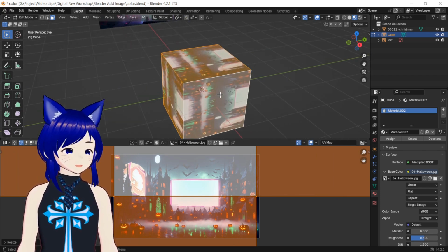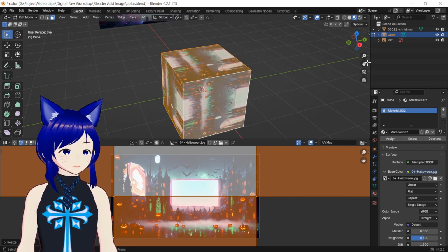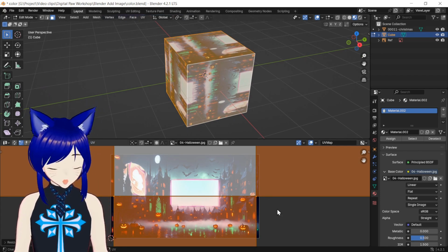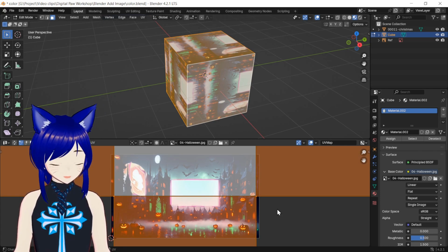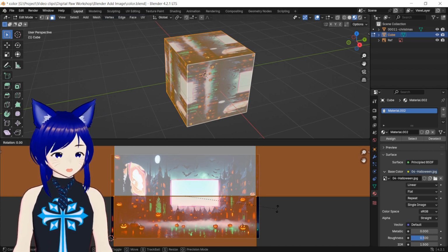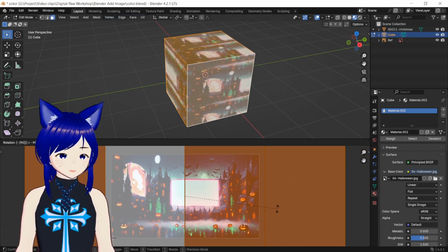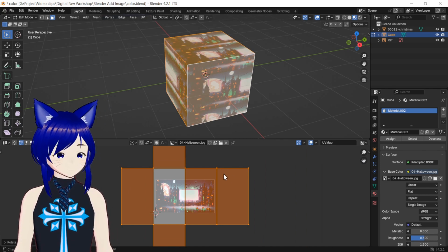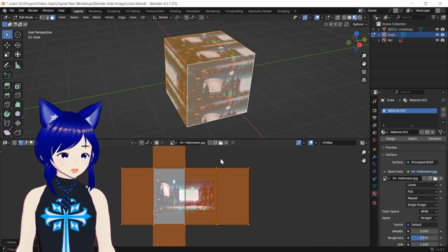As I do, it did reduce the size, but you see, it's kind of got it turned sideways, and I don't understand why Blender has it one way here and not the same way there. So I'm going to hit down here, make sure I get everything. No, I don't want size. I want R for rotate. I'm going to hit -90 because I do want about 90 degrees. Now, this way is Y-axis, this way is X-axis. So you got to remember that.